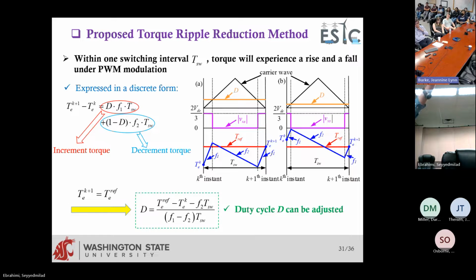But the reason I'm saying it may not be fair is that when you have higher switching frequency, you also need to consider switching losses. So what if you have higher switching losses? That's why I'm saying that to make a bold claim, we have to investigate more. But so far it's very promising, and we have extended this and submitted it to the journal.